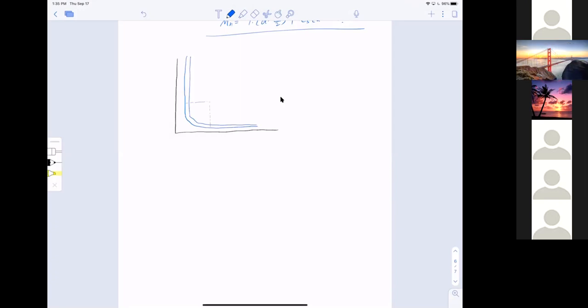So this is the bending center, the center of bending. Now, when I put my bar, I'm going to use red, the bar sits right here. The bottom of the bar is in contact with the stirrup here, so the center of the bar lines up with the center of the bending radius.